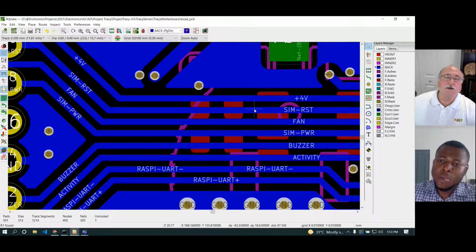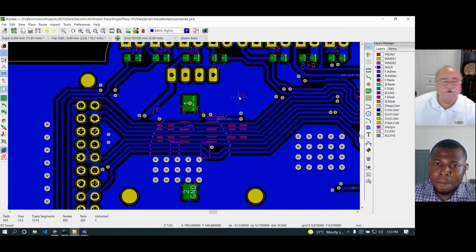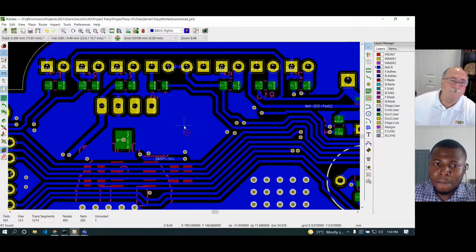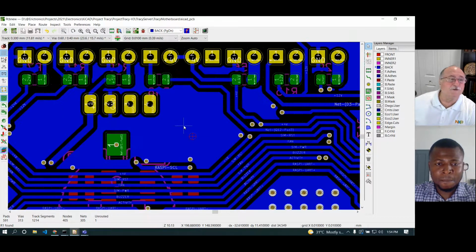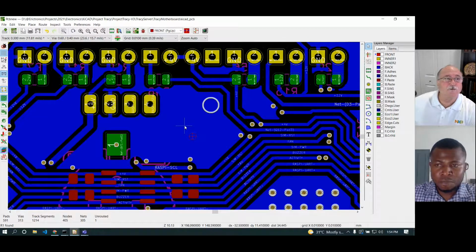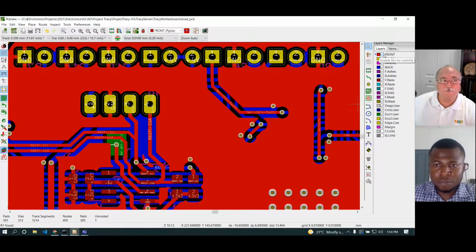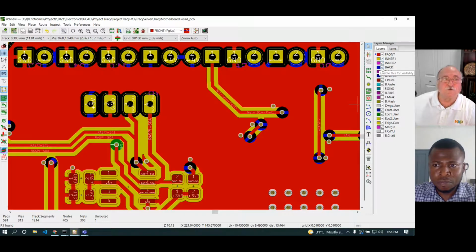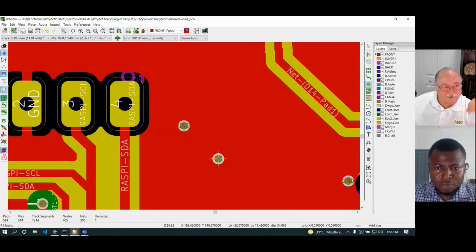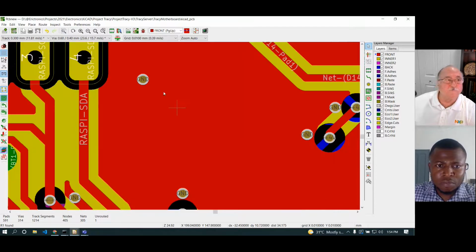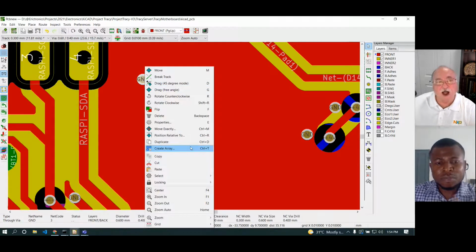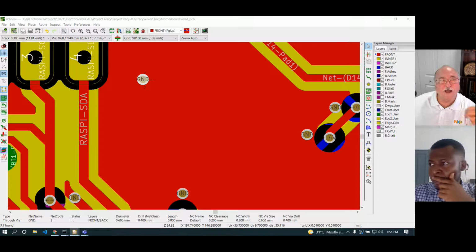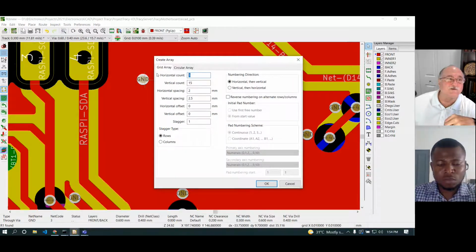And again, the amount of energy per square centimeter is determined by the switching speed of the driver. So that displacement charge density, the higher that is, the faster it's changing from one voltage level to the next, the higher it will drive the magnetic field in the adjacent traces.